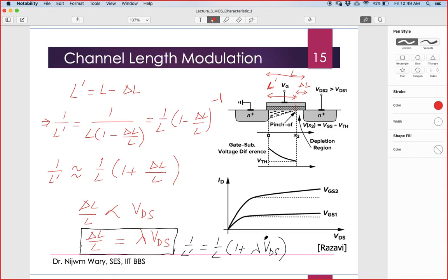I'm saying that by increasing VDS we are disconnecting the channel from drain to source. Okay, basically the pinch off is happening. Yes, sir. If we increase VDS so high that the whole channel is depleted, so you are telling that this becomes very short. Yes, sir, very short. Then is the current constant or is it going to vary, sir?